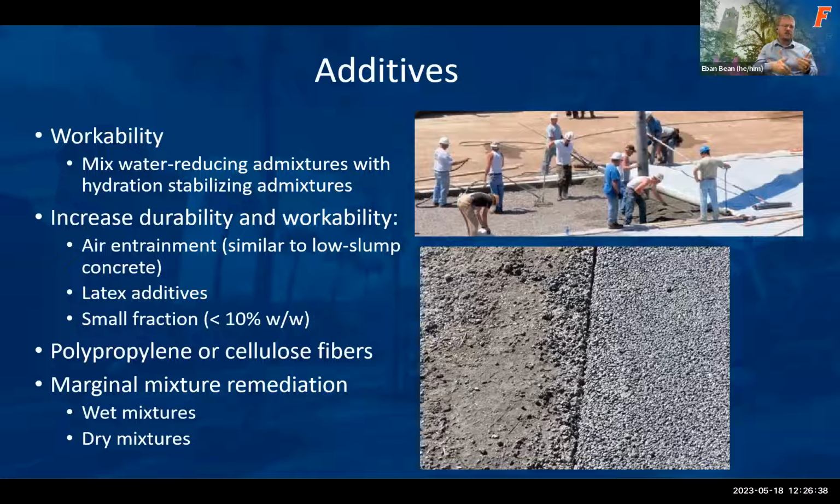The other side is if it stays too wet for too long or it has too much cement. And you saw in the previous slides where we had the drain down that occurred and it kind of sealed the bottom. And that can really reduce the performance as well. It can still function. You have the storage that's just in the pavement itself, but then it takes a while for that to laterally flow out of the system and into other areas if it's completely sealed on the bottom.